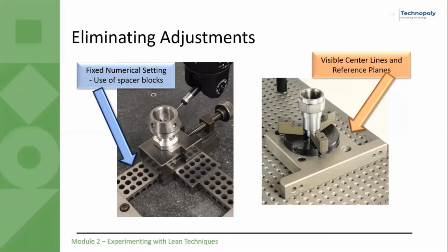Many operations performed on one machine have elements in common, where similar things are done but with different dimensions, patterns, or other functions. The LCM system makes these common elements into a mechanism that can handle the different functions needed. During changeover, the mechanism stays in the machine and only the functions change. In this sample photo, LCM is demonstrated by the clamp.